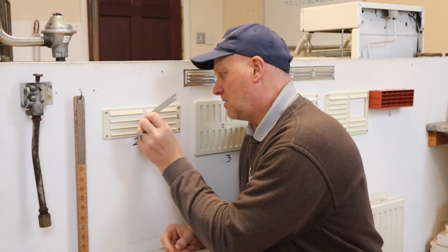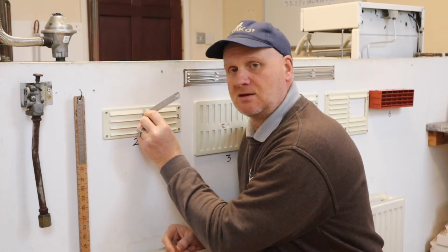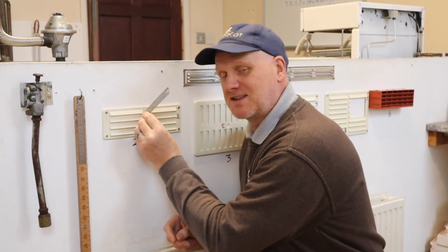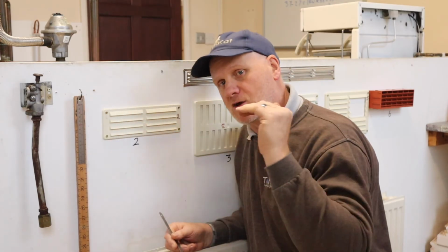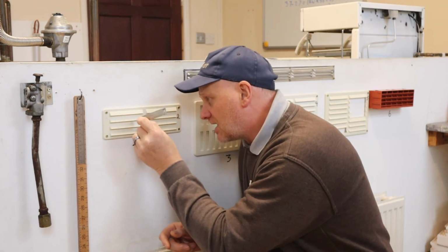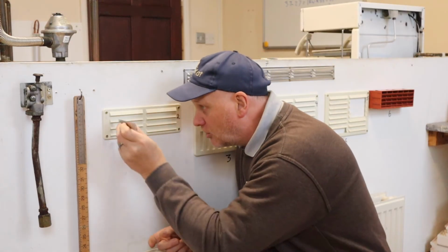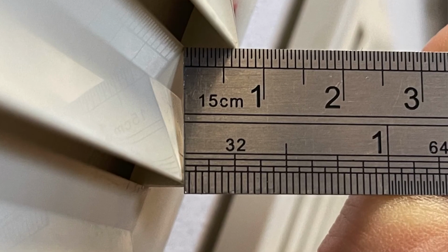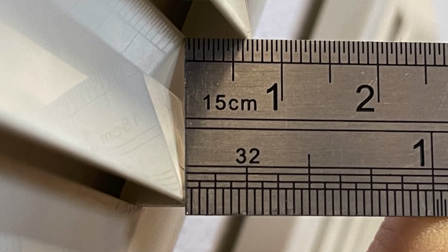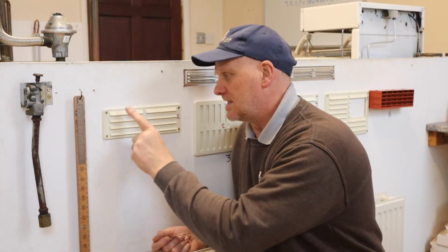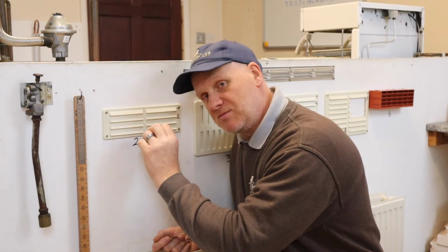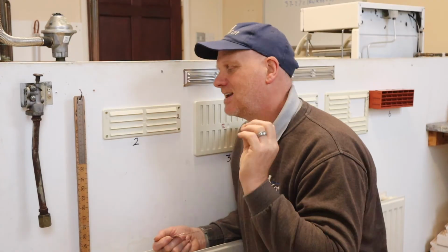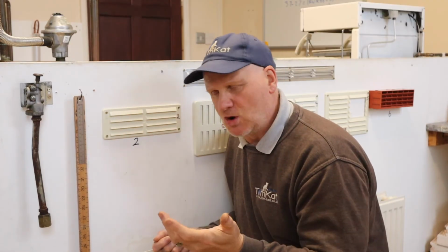And the next thing we need to do is place the steel rule on the same angle as the vent, because these are deflected, so it stops air going straight through it. So if I go onto that one there, flick it over and measure that there, that is coming out at 5mm. So 95mm long, 5mm in depth. Now an air vent cannot be smaller than 5mm and cannot be larger than 10mm. That's to stop insects and rodents getting in.